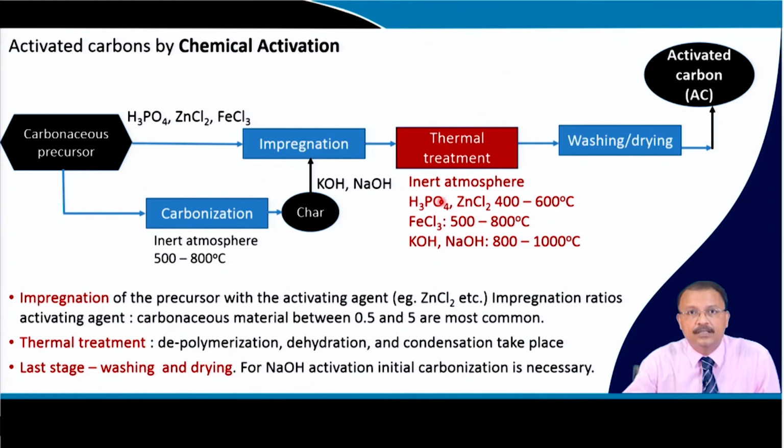If you are using H3PO4 or zinc chloride, then 400 to 600 degree Celsius, and progressively it goes higher if you are using iron chloride, and sometimes you would use alkali material like potassium hydroxide or sodium hydroxide, then it is quite a high temperature you need.